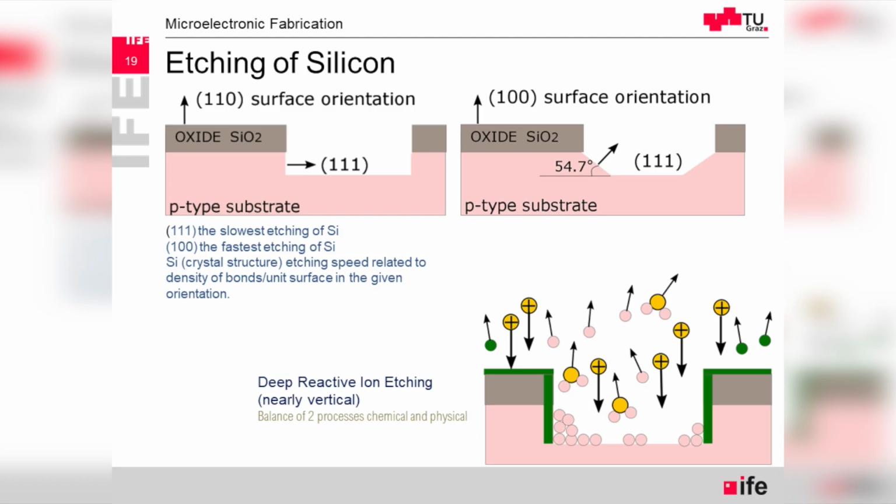But basically, if we need something like that, what's being done is in two phases. First phase, with the RF source, the plasma is introduced. We have the ions, which are directed towards the surface, and they are bombarding the surface, physically removing the atoms of the material that is being handled.